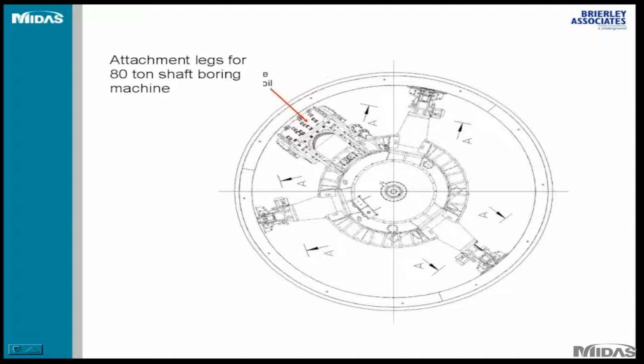There is another question about whether the shaft annulus was grouted from the surface through the segment boards. Yes, in these segments you can pump in grout. Once you have it in place and reach the desired depth, you can start the grouting process. There are special openings or access points where you can inject grout behind the shaft.